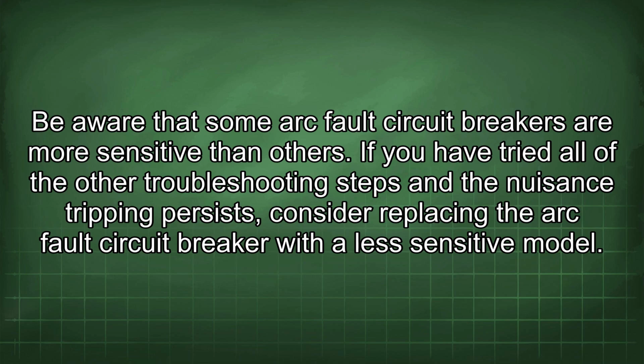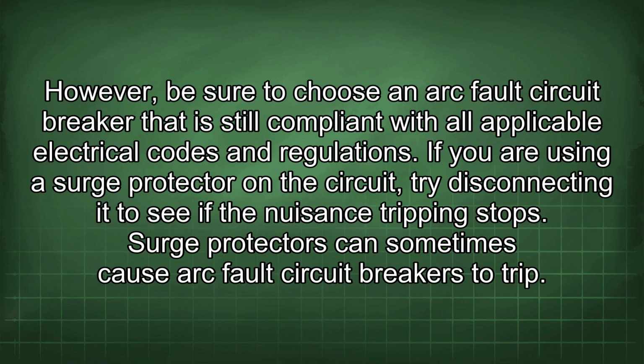Be aware that some arc fault circuit breakers are more sensitive than others. If you have tried all of the other troubleshooting steps and the nuisance tripping persists, consider replacing the arc fault circuit breaker with a less sensitive model. However, be sure to choose an arc fault circuit breaker that is still compliant with all applicable electrical codes and